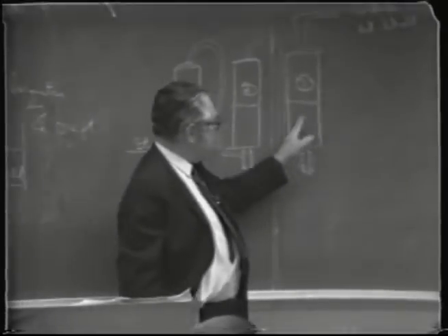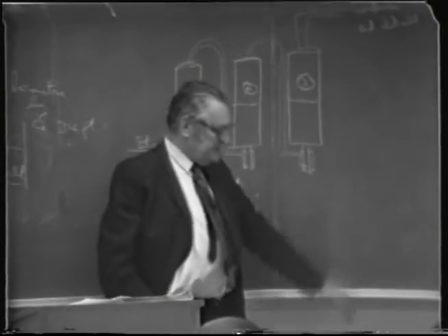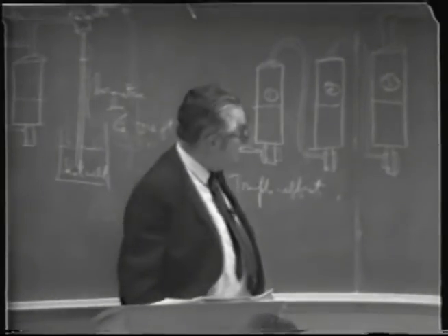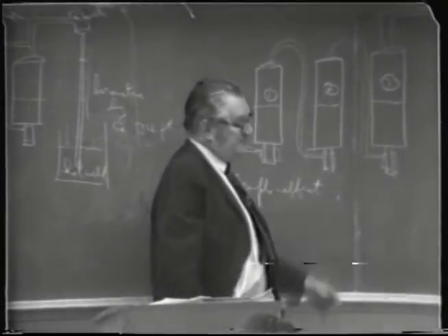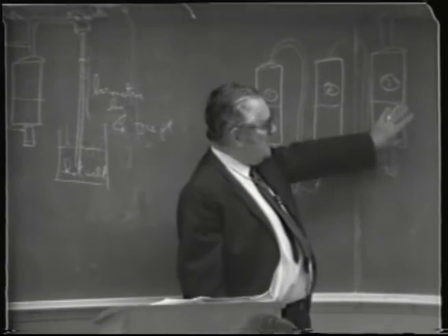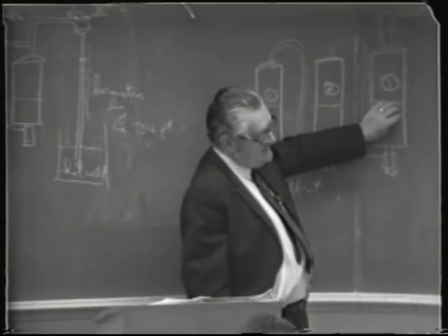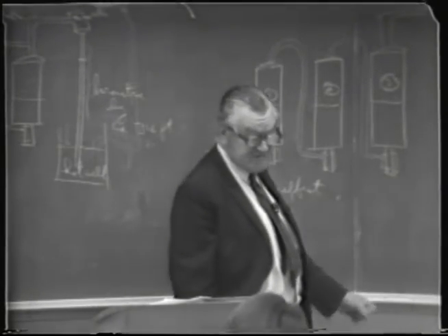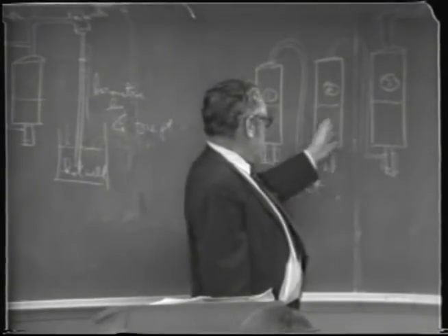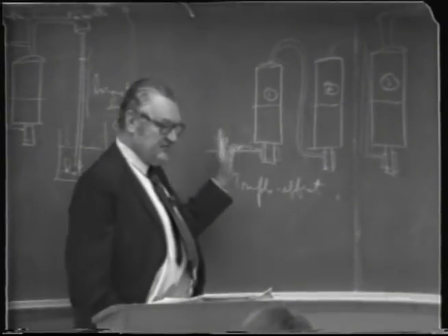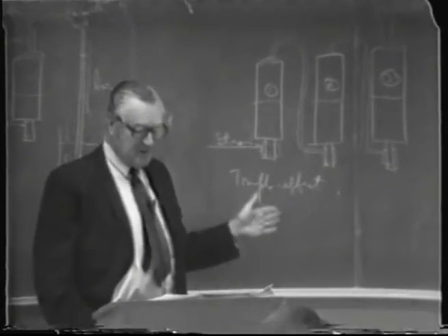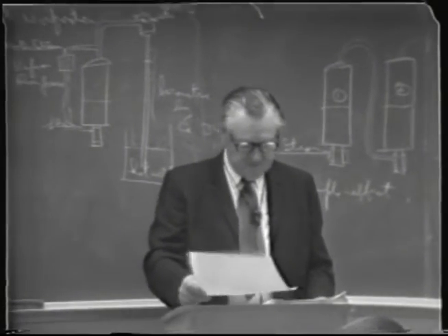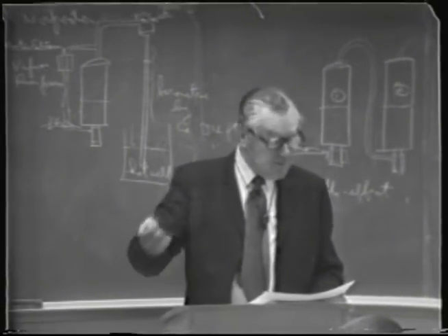And in practice, these pressures have to differ by the order of at least several pounds per square inch, just as a rough guide. So even though we may not be able to operate this at, let's say, 2 or 3 pounds per square inch absolute, you'll likely have above atmospheric pressure over here. And so you have the problem, with respect to organic materials and food materials, of thermal degradation of the flavors and components in the food materials.